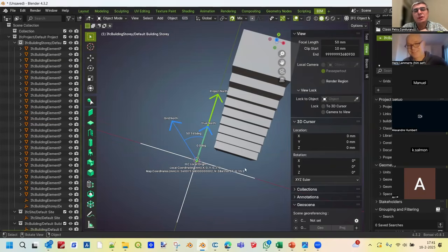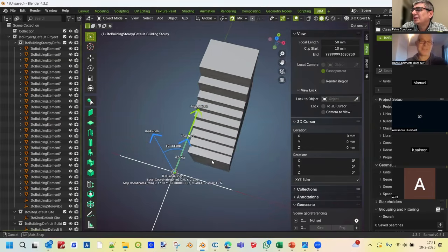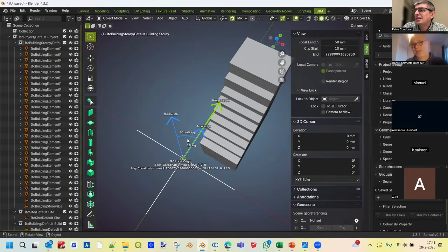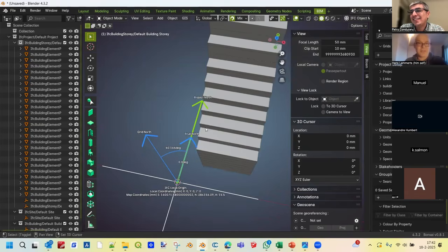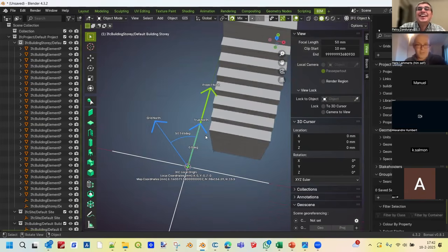Did you get any reply from Dion on what he thinks about it? Well, he says for sun studies, like the true north, the difference between grid north and true north for the Netherlands is about half a degree. Who cares? I'm not doing sun studies, but if I would, I could work perfectly fine with grid north, because it's the grid. Let software handle it. Don't bother users with the difference. That's totally my opinion.